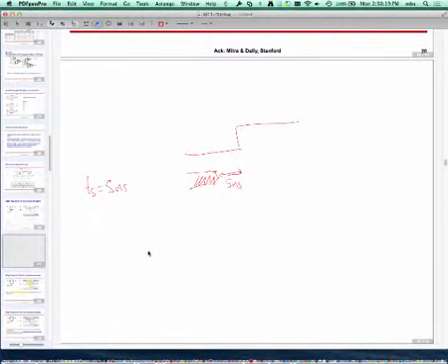If on the other hand setup time is, say, minus 5 nanoseconds, then it is saying that until 5 nanoseconds after the clock, D can keep changing, but then it has to become stable. So it just takes us in the other direction.